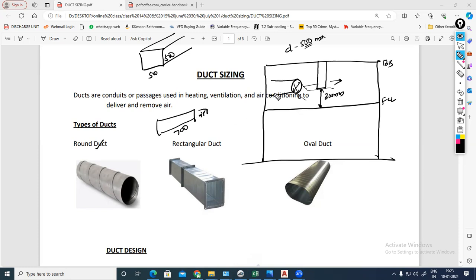Then the duct shape we can change, and that duct we can take this way. So not that much velocity issue, not that much head loss issue will arise, because a rectangular duct is flexible only. So with respect to the site condition, easily we can modify it, and space saving will be there. Space is also a concern, because when you are placing your round or oval duct in the corner and all, a lot of space issues can come.